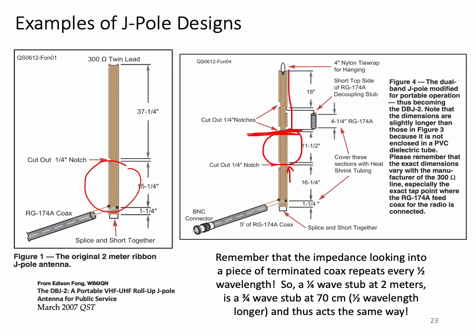So by placing an extremely high impedance at the top of the 70 centimeter antenna, we isolate it from the rest of the antenna, and it has to be a low impedance at 2 meters, and this is simply done by adding a quarter wave stub for 70 centimeters at the top of the 70 centimeter half wave. That's this little portion right here. So at 70 centimeters, the stub looks like an open circuit. Remember, this is a short circuit on this end, and therefore, if it's a quarter wavelength long, it transforms the impedance from a short to an open.